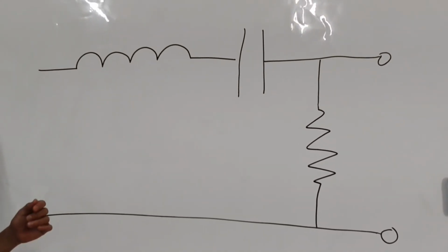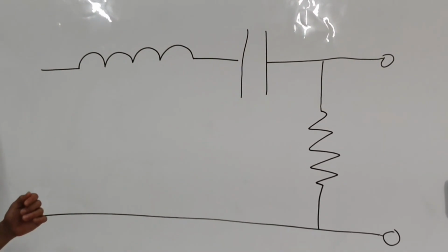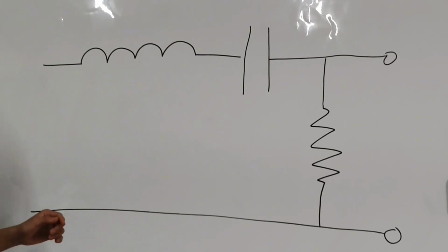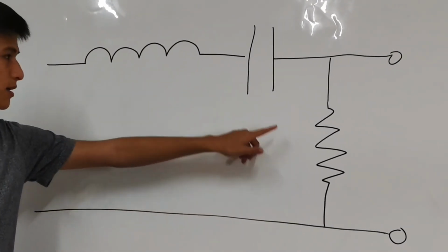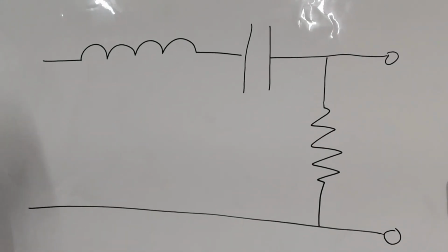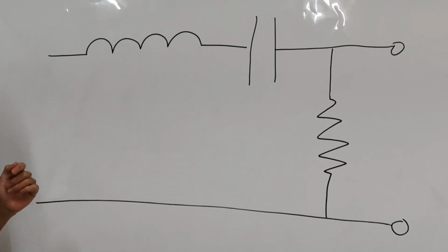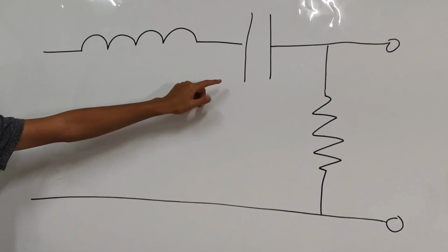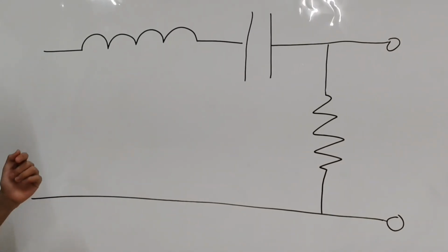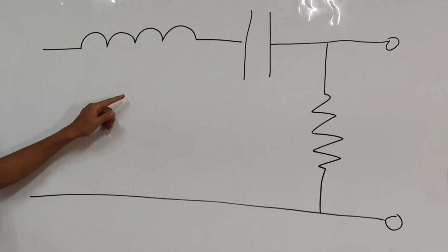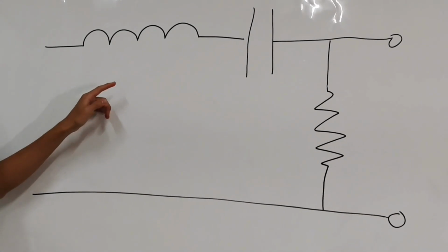In practice, a bandpass filter can be realized using an RLC circuit, where the combined effect of the resistor, capacitor, and inductor determines the frequency response. At low frequency, the capacitive reactance is large, which limits the signal transmission, and at high frequencies, the inductive reactance becomes dominant, again reducing the output signal.